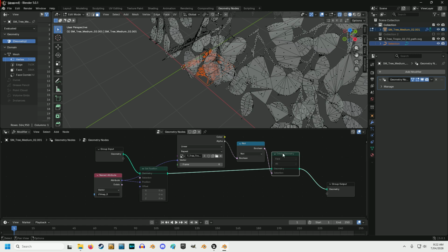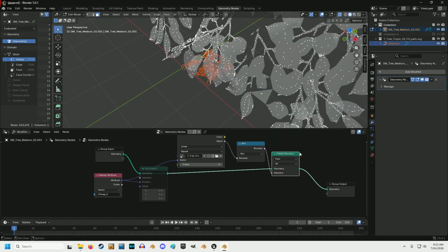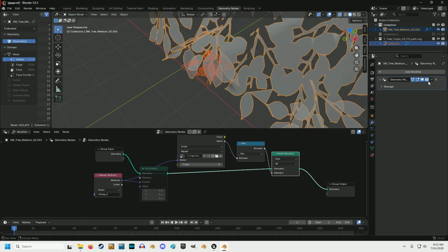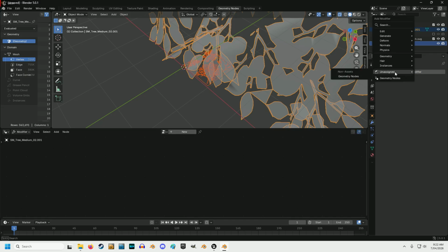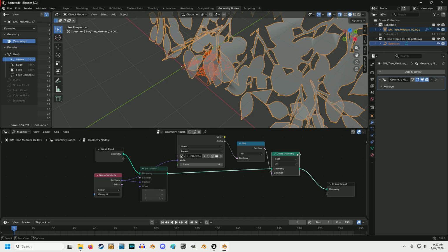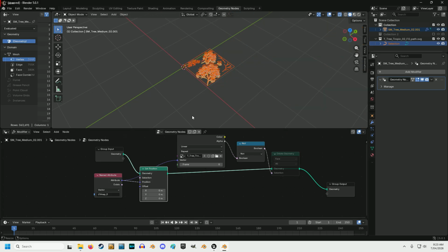So what I'm going to do now is unmute this one, and it's just dumped a whole lot more of the geometry, which is what we want. I'm going to reapply that again. I just have to go to object mode to reapply the modifier. Apply that again, and then again get the geometry nodes back to use them again, because we're still using part of this set position to put everything flat again.